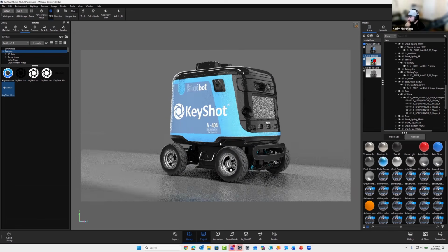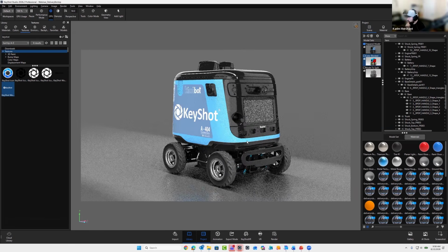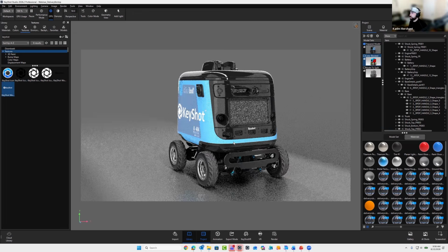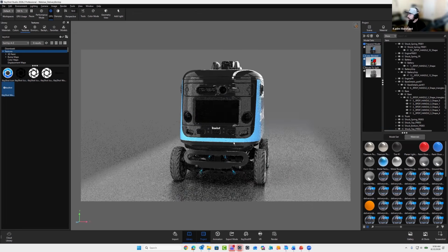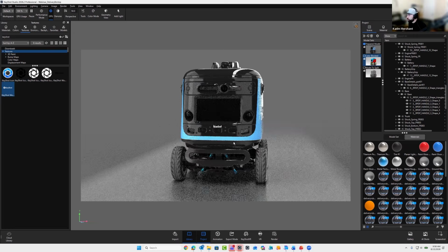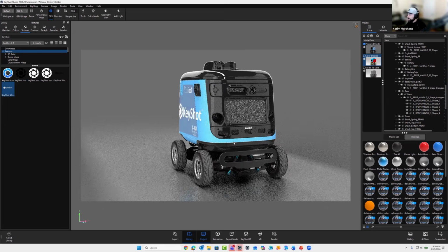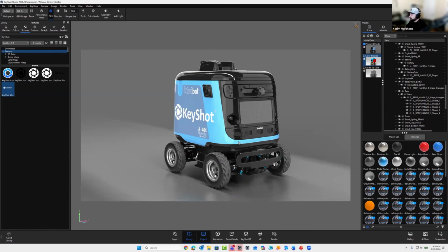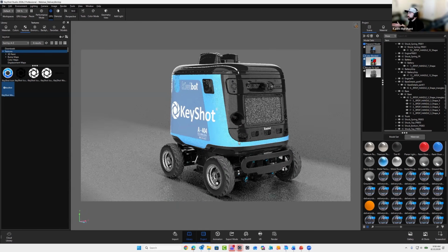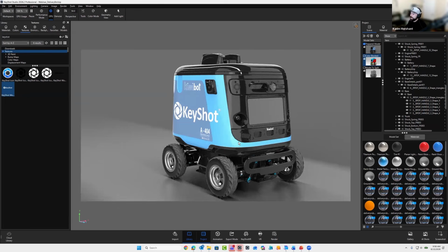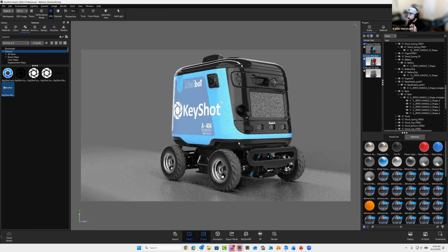I'm assuming that you're probably using an emissive material to try to recreate that LED. The thing is that an emissive material is an effect on the surface that you're applying it to. It's not actually producing light out and lighting your scene. So typically, if I'm trying to create an emissive to generate an LED, but I want light cast, I'll pair that emissive with a spotlight or something casting onto the area I'd like it to come out of. And then I just hide that light and match the light color to the emissive. So it's a mixing of actual physical lighting along with the emissives as well.